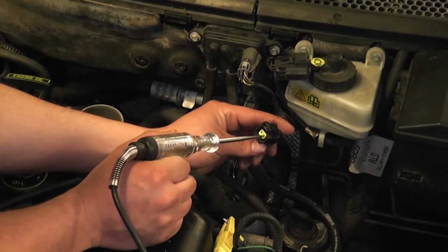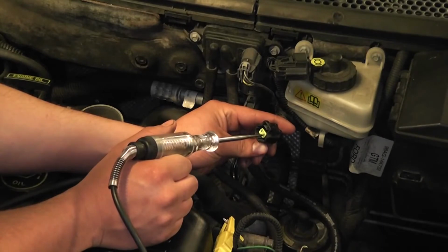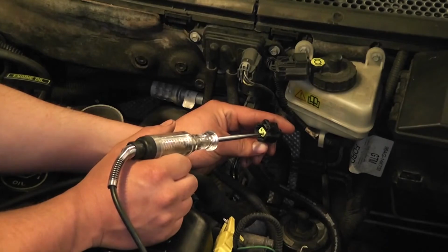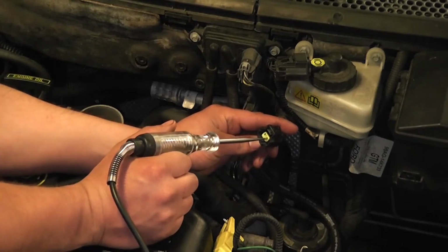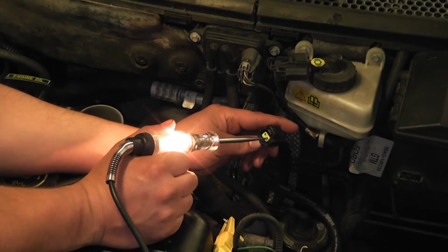I'm going to command this circuit on. So I just hit on. Test light did not light. That's not what we want to see. Turn it back off. Okay, one of the things that we need to be careful of with this kind of situation, sometimes a computer will turn an output off and completely disable it. Now it's working. Okay, good.